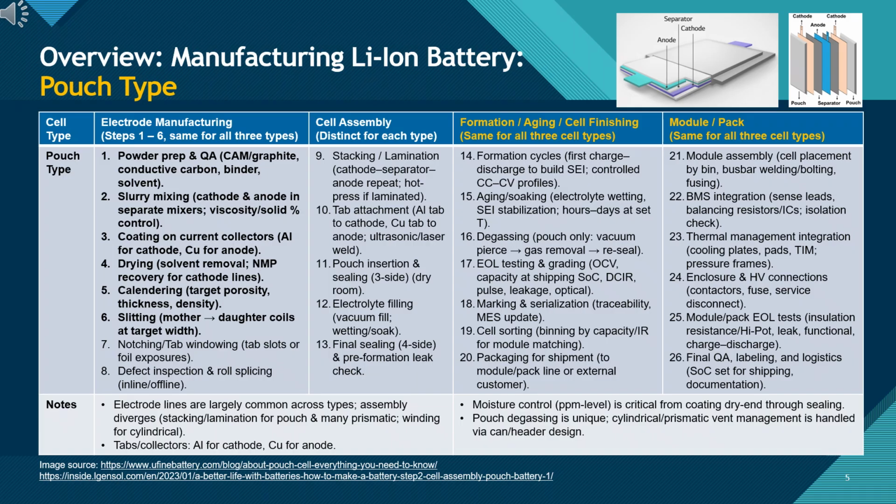packaging. These steps highlight how pouch cells are built layer by layer: coating anode and cathode sheets, stacking with separators, injecting electrolyte, sealing the pouch, and completing formation. Two diagrams on the slide visually illustrate the internal structure of a pouch cell, showing how the anode, separator, and cathode layers are stacked and enclosed in the pouch film.